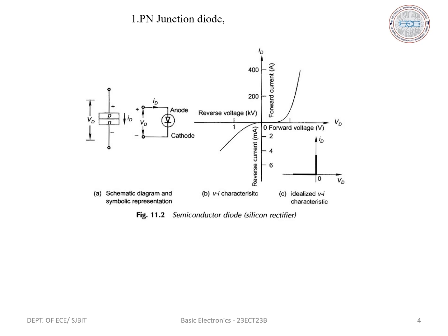If the P region, that is the anode, is connected to the positive terminal of the external DC source and the N side is connected to the negative terminal of the DC source, then the biasing is said to be forward biasing. In other words, the diode is said to be forward biased. Generally, a resistance is connected in series with the diode to limit the current flowing through it. The current I is a conventional current that flows in the circuit due to forward biasing.